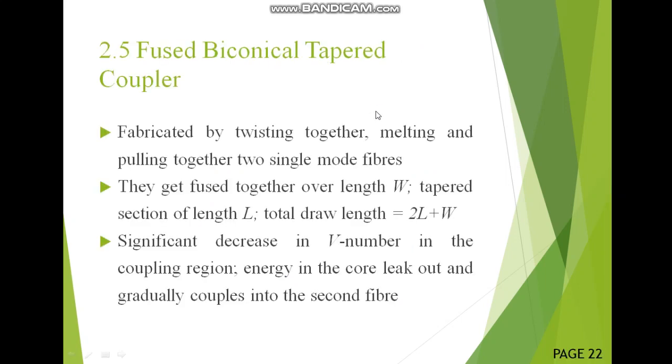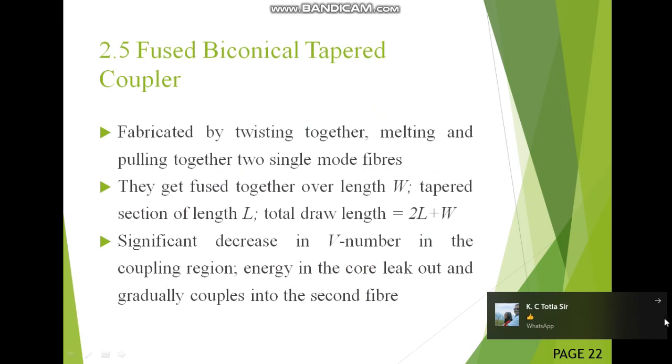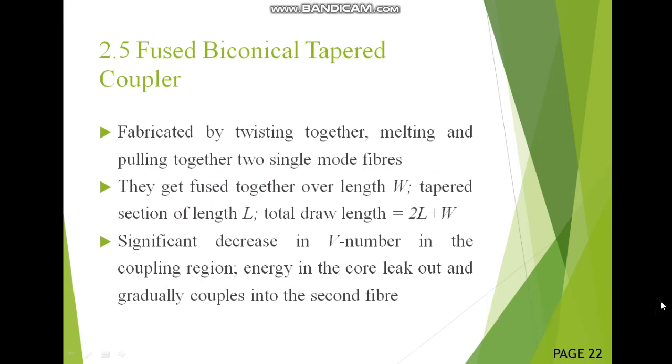Now just discussing its fabrication and how it is denoted. It is fabricated by twisting together, melting and pulling together two single mode fibers. They get fused together over length W, with a tapered section of length L. Total draw length is 2L plus W. This we have seen.